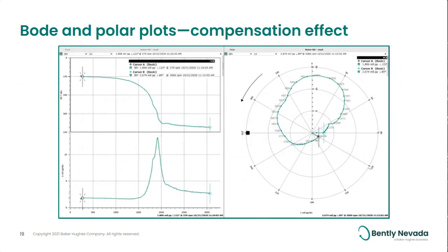Okay, so here we have a Bode and a polar plot, and they both have slow roll issues. But I want to show you which one is easier to compensate mentally, okay? So here we've got 360-degree phase shift. How are you going to figure out where your resonance is? Because you're looking for that peak and 180-degree phase shift. Here you got 360. Same on the polar, although it's much easier on the polar.